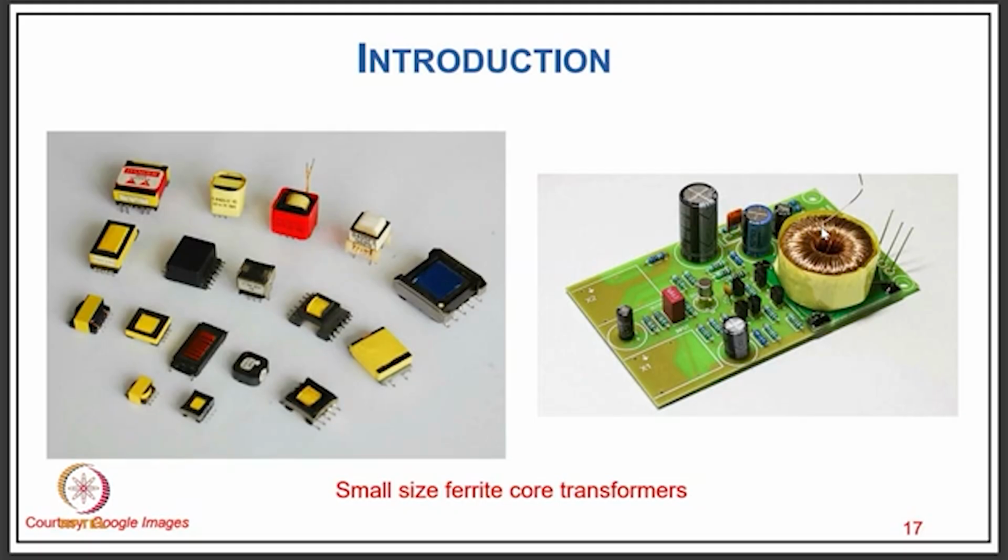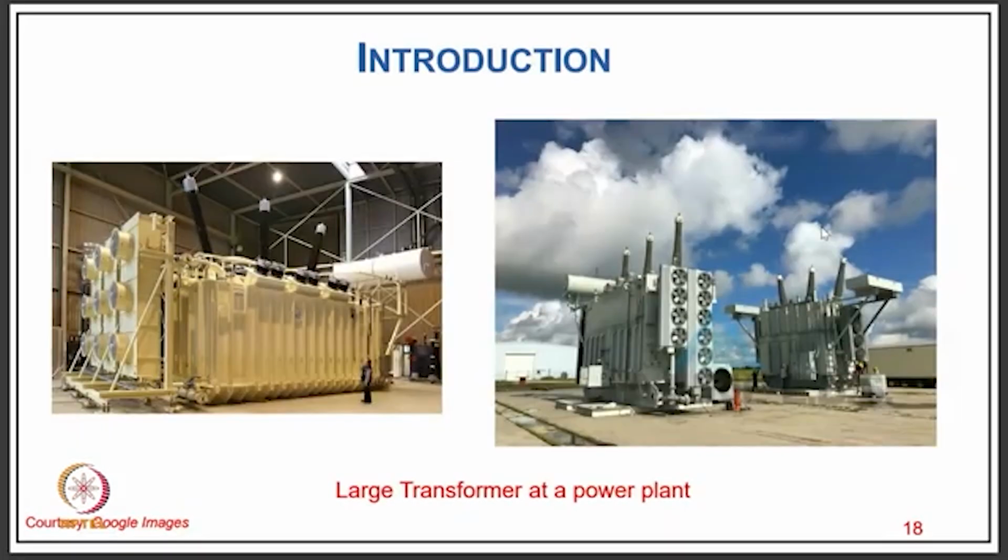isolated supplies. A typical example is the computer power supply, where you need power supply for the cooling fan, you need the power supply for motors of floppy disk drive, hard disk drive, you need the power supply for your processor. So all these DC supplies are isolated and they are of different voltage. So you have, in the transformer, several secondaries which give you different voltages, where you keep different number of turns also.